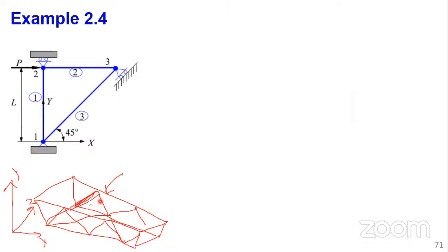You can imagine for a structure like this truss bridge, with all these members, how many degrees of freedom there would be and what the size of the matrix would be. When we go to 3D, each node has 3 degrees of freedom times the number of nodes, and that will be the size of the matrix. That's why we need the computational power of computers to help us solve these matrices. But we have understood the basic principle of operation of this matrix.